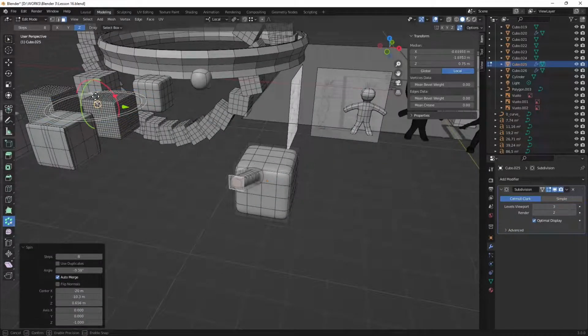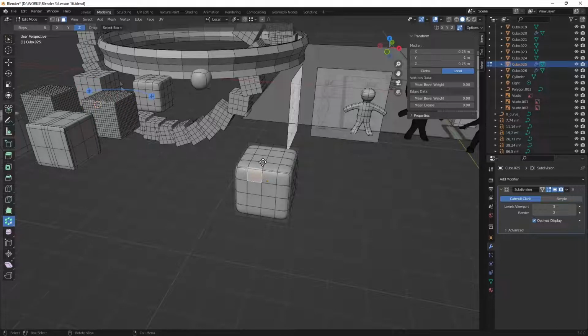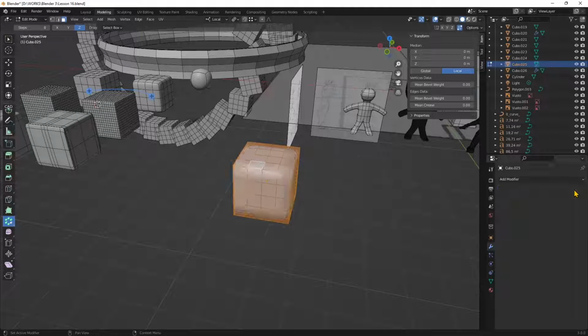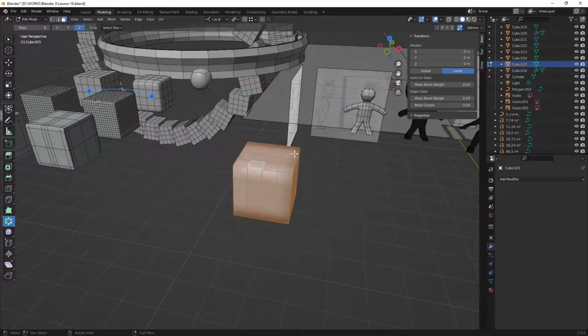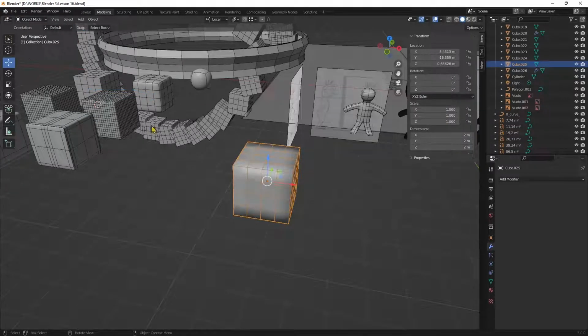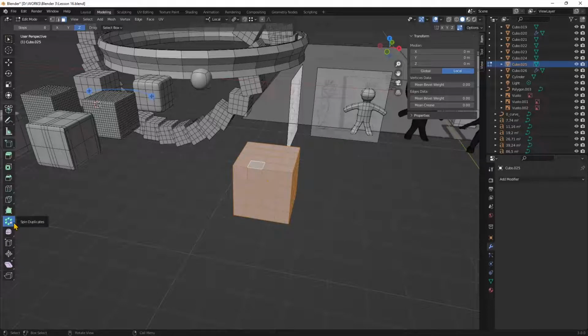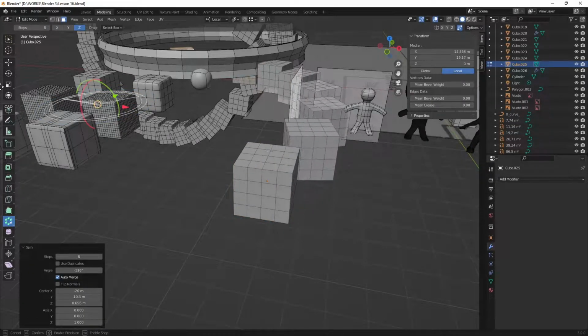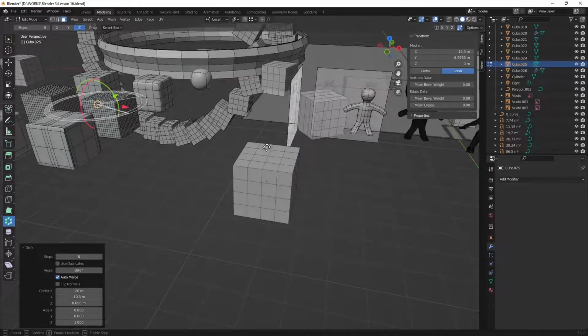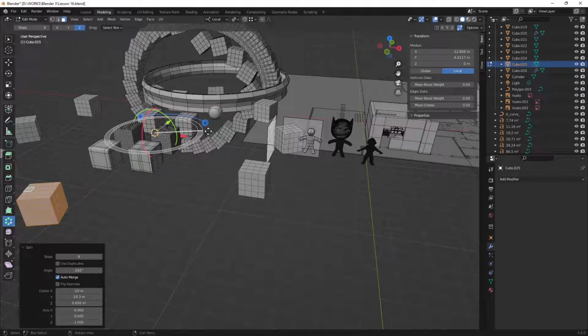And so you can do this with a single polygon, or you can press A and use the overall polygon here. Let me just deactivate the subdivisions and turn into the flat mode. So right click and do shade flat. So this is gonna be like a simple cube. And let's go back to edit mode. Okay, now if I do that again with the spin duplicates, you can see I can create copies of these. Again, could be like chairs around the table, things like that.